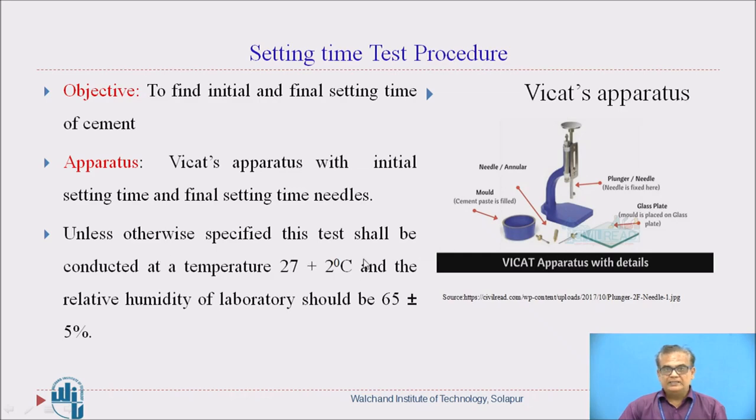Now this particular test shall be conducted at a temperature of 27 plus or minus 2 degrees centigrade, and the relative humidity of the laboratory should be 65 plus or minus 5%.